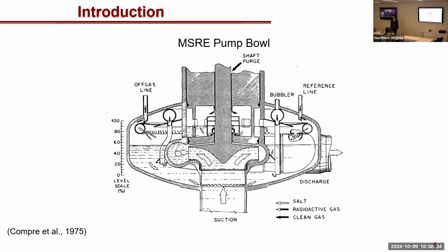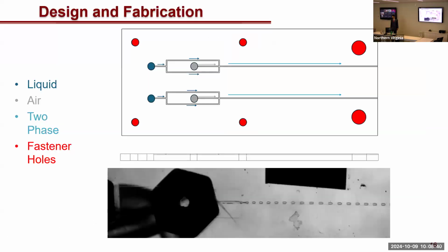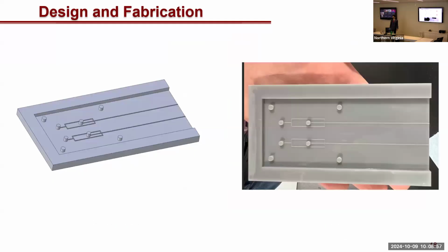At the beginning of your presentation, you talked about constructing the test plate and all that. Would there be significant changes to that design? Yeah, for example, here we would use a width probably closer to 0.3 or 0.25 for these square channels. For the mold, we would have to change the mold for that.